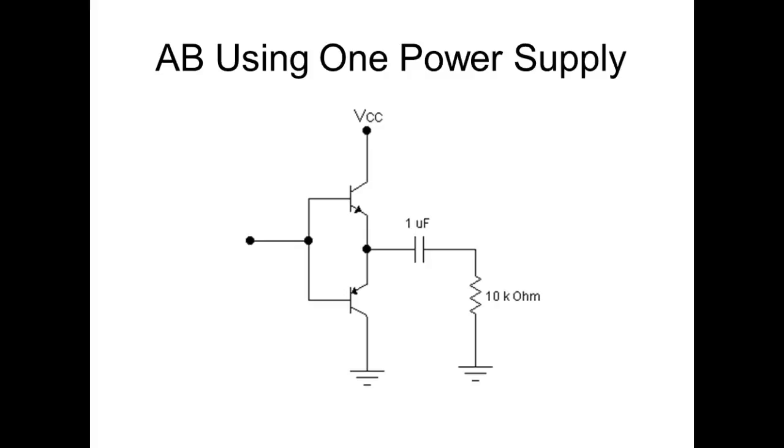So what does the complement mean of two transistors? It means they have the same specs. It's just one of them's a what? PNP, and one of them's an NPN. So these guys have got to be complementary pairs, or they call them complementary pairs. So ours, we're using the 2N3904. So this guy here would have to be a 2N3906, which is the complement pair.